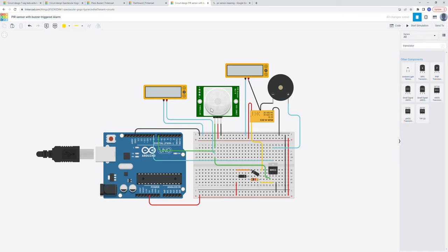This is the PIR sensor. It actually triggers a signal once any movement is shown in its perimeter, and then the Arduino identifies this movement and triggers a sinusoidal signal into the buzzer, and the NMOS transistor here opens the path, the bias for the relay, which enables the relay control to short circuit the negative terminal of the buzzer to the analog ground.